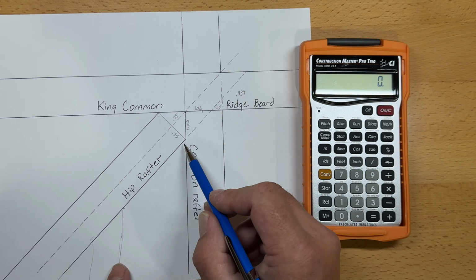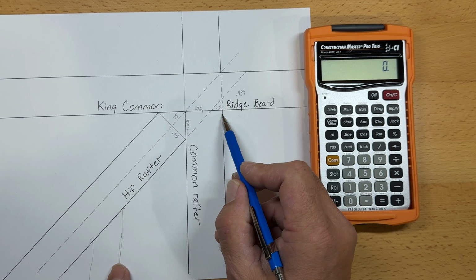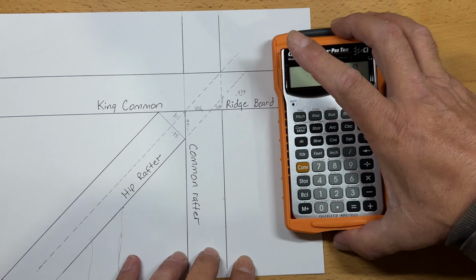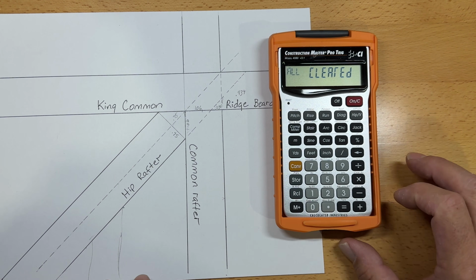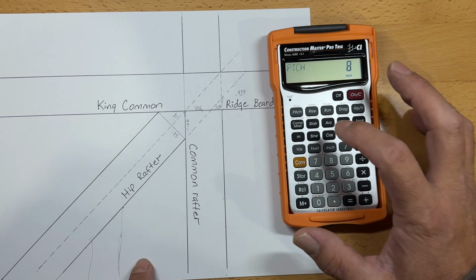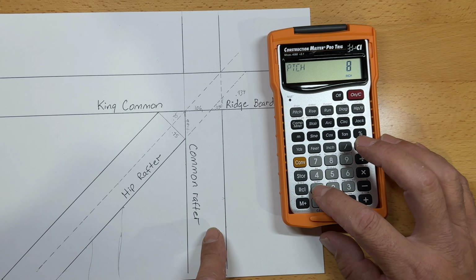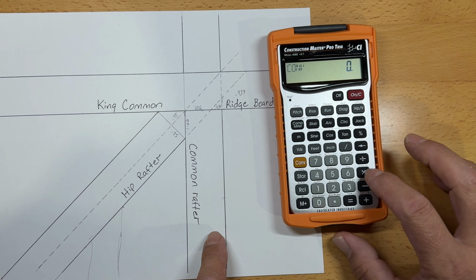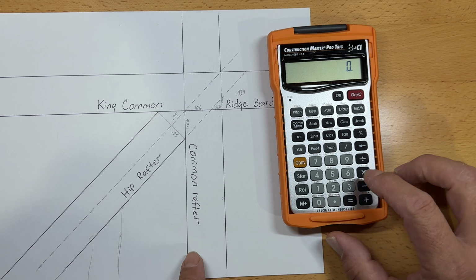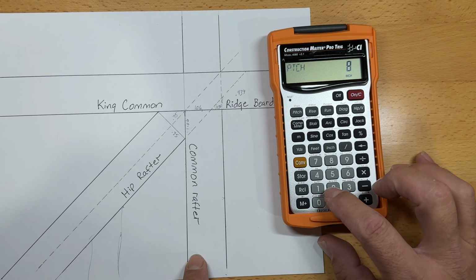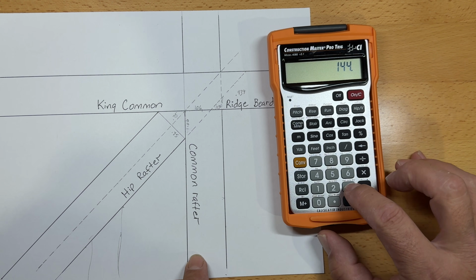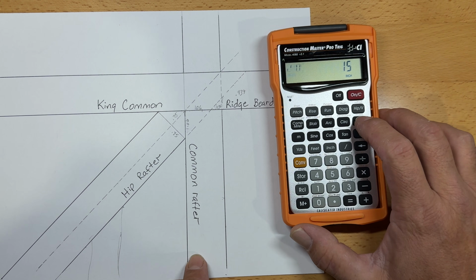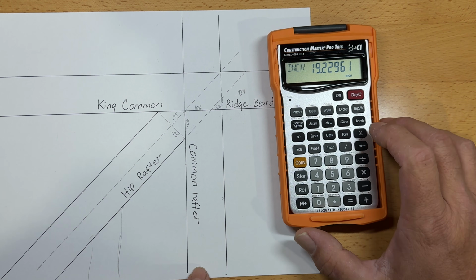So in order to do that, we have to go to the theoretical point if this common rafter extended through where the hip rafter would meet it. So the way we do this is, let's clear this out, and we'll go back to our 8-inch pitch, and this time it's going to be 12 feet. Actually, let me clear that out again. We'll do it in inches so we can get it more accurately. We'll do 8-inch pitch, and then it'll be 144.439 inch run. Now when we hit our jack rafters, we'll start off with 16,